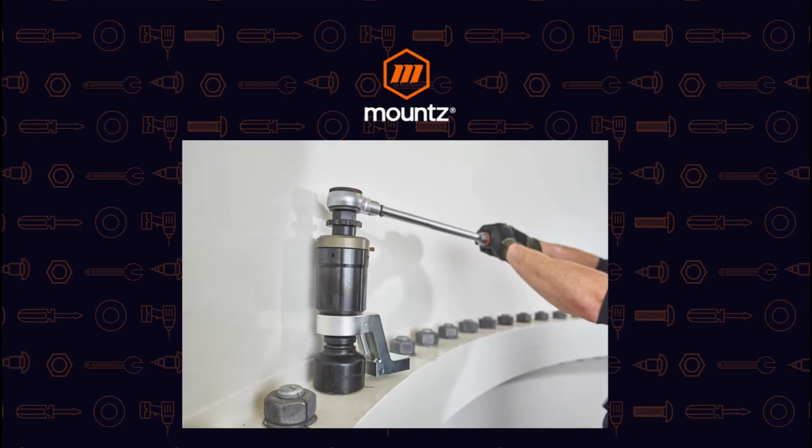And so if you have, in this case, maybe an 8-to-1 multiplier, if we have a torque wrench, just a simple standard torque wrench, and we set that to 100 foot-pounds, as we use this multiplier, it's going to deliver 800 foot-pounds at the end of the socket there. And so we're using a minimal amount of input, and we're getting whatever value we're looking to achieve at the end of that use of the torque multiplier.